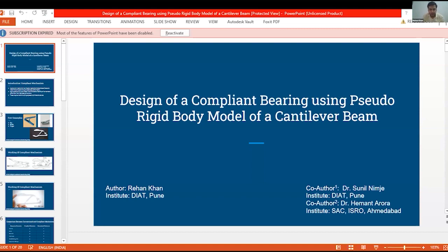That is the working of a compliant mechanism. We can compare both the mechanisms here. Both are the same mechanism in terms of their functioning; they are basically gripper mechanisms. The one on the left-hand side is a conventional mechanism, and on the right-hand side is a compliant mechanism. The only difference we see is that instead of conventional pin joints, there are flexures or thin sections used in the compliant version of the same mechanism.